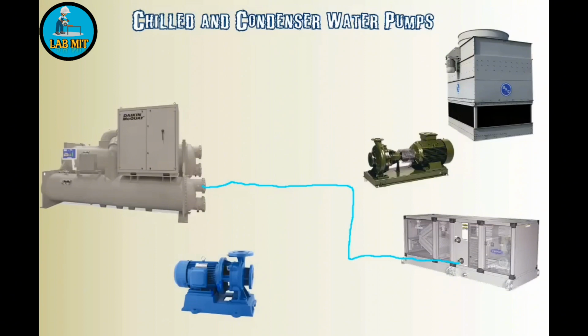you fill this coil with water, you always want to have the outlet of the water coming out the top of the coil. And the reason why is you want this to fill up with water before trying to pull it out. It's possible if you were to supply this coil with water coming into the coil from this direction, that the water may not actually fill the coil and you'll get air in this coil, which would mean that you're not going to get cooling on the upper portions of this coil if there was just air there, and water would flow in and then come down and get sucked out the bottom. So the reason why they fill it up from the bottom is that way you make sure you pressurize the coil and get all the air out of that coil.